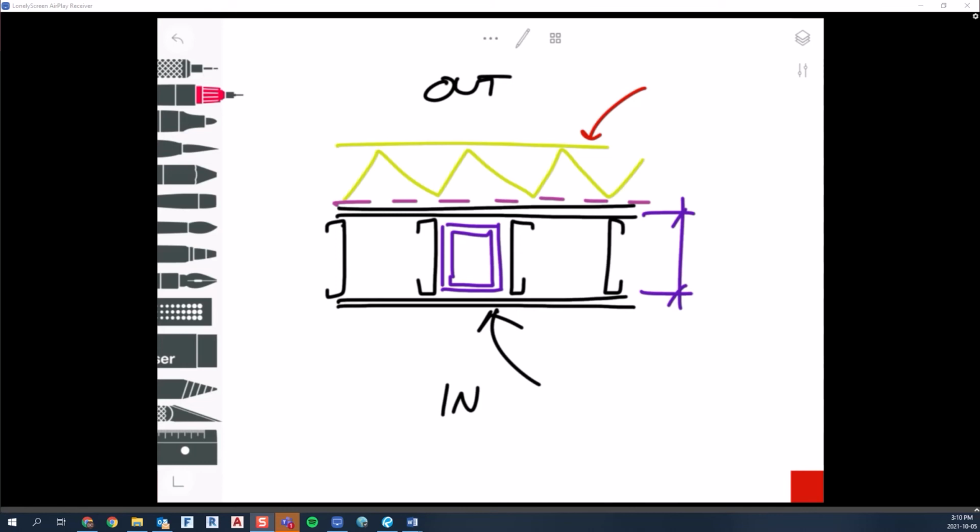Another approach that I think I forgot to mention: when we had a 6" column with a 6" stud, we started changing the stud size to a 203. Then you could get up to your 178 by 178 column, and it would still be buried in the wall.